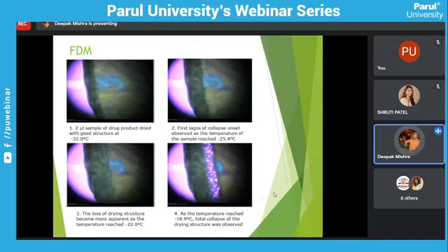After we increased the temperature and went to minus 25 degrees, the collapse begins. You can see it in the middle line. This is the beginning line. The first sign of collapse, the onset, was observed as the temperature reached minus 25.4. So in this technique, we can also check our product molecule. Our molecule collapses at minus 24 or minus 25.4, above minus 25.4.